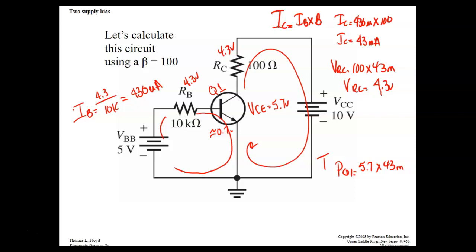And that's very, very important to know because it's a solid state device. If we know the voltage from collector to emitter, and we know the current flow through the collector, by the way, the collector is the reverse bias junction, so it's the one that's dropping all the voltage. The base to emitter is going to drop about 0.7 of a volt. So that 5.7 volts is being dropped in the collector junction, so the collector junction is going to get hotter. We'll look at that later on when we start heat sinking and stuff like that.